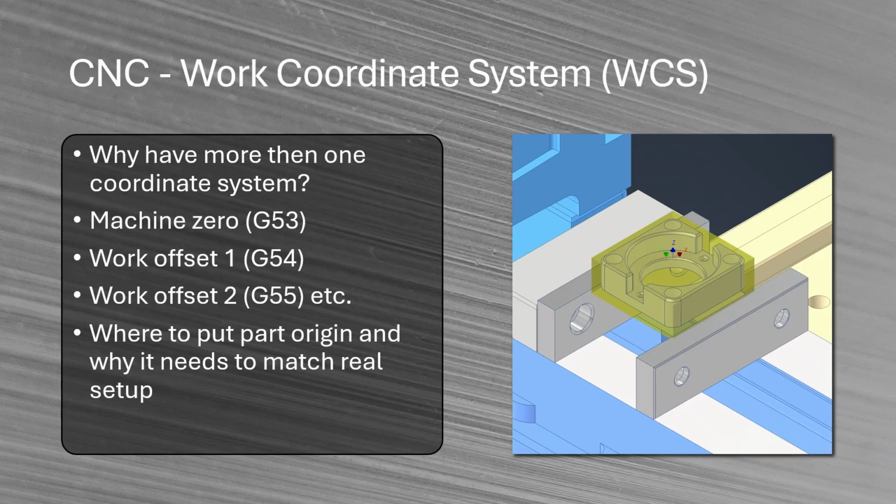So another thing that I need to tell people when they have cammed a lot of times, because the question often comes up like, where do I put the origin of the part? A lot of people may think that that doesn't really matter, but it makes a big difference. A lot of people would let it remain in the default position, which I believe is in the center like this. This is fine, but we should keep in mind the difficulty it may be when we actually machine the part, because of course the real world zero needs to be the same as in the CAM.